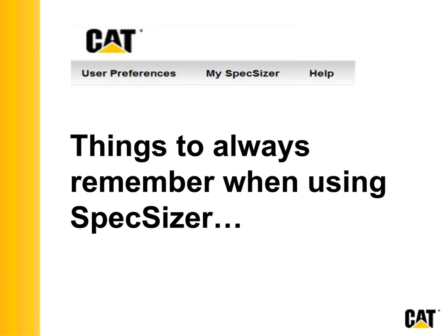So that's pretty much what we have as far as help is concerned. Okay, to wrap up here, I wanted to go over some things that you should always remember about sizing your genset. Really, it's not real complicated. I've talked about it 2 or 3 times through the presentation, but do you remember where I said don't sequence all your loads in one load step? I've seen very few sizings in the thousands and thousands that I've looked at over 10 years where the application required that all the loads be sized in just one load step.